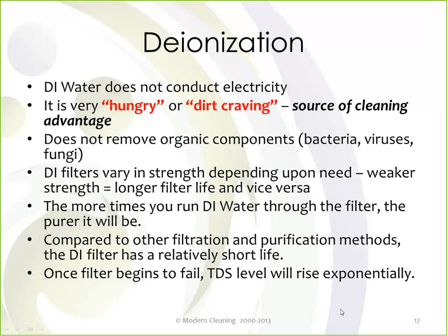Sure. But also, DI filters vary in strength depending upon the need. We don't need the really super strong DI filters for what we do, and they're very expensive anyway. But the weaker the filter, usually the longer the filter life, and vice versa.